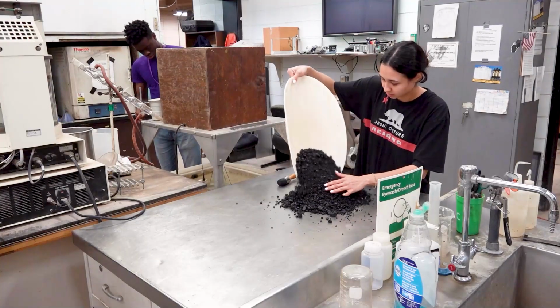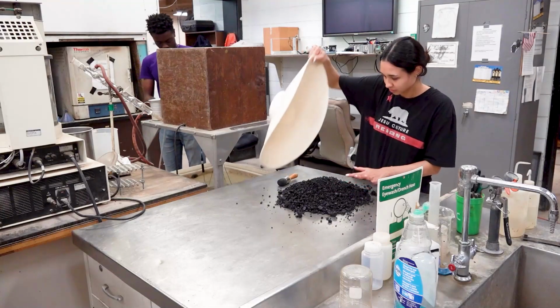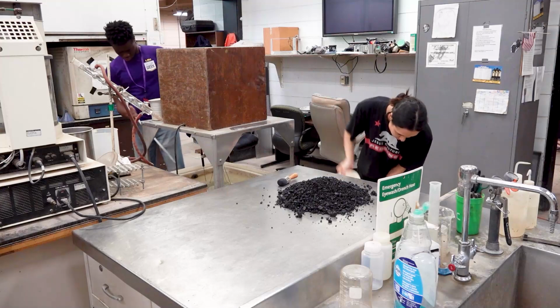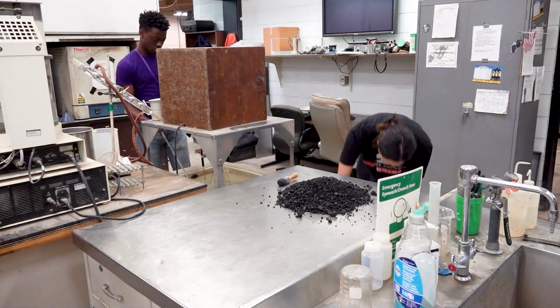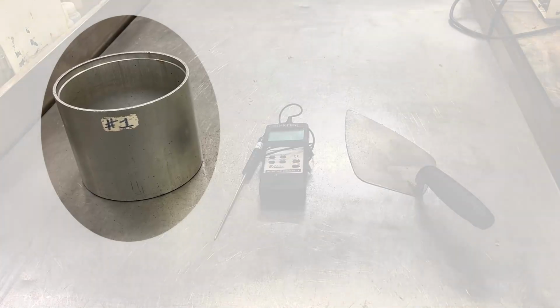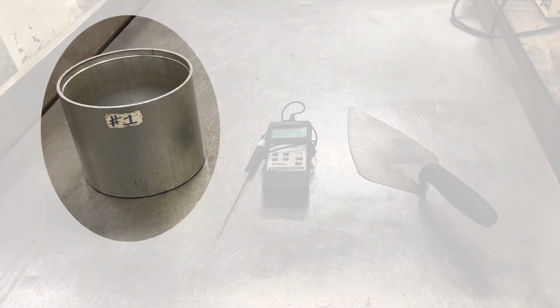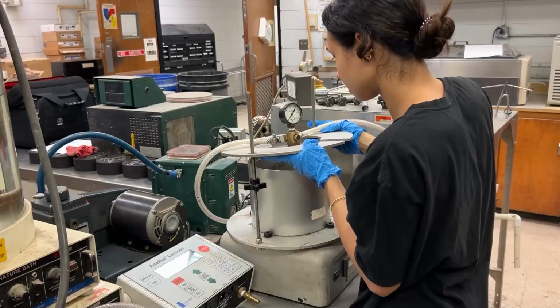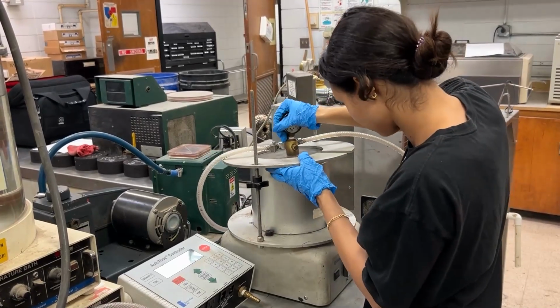Listed below are materials needed to perform this test. A 6,000 gram sample of asphalt material in accordance with DOTD S203 from the Material Sampling Manual. A glass, metal, or plastic pyknometer with a volume defined utilizing a glass capillary stopper, capillary lid, or glass plate.